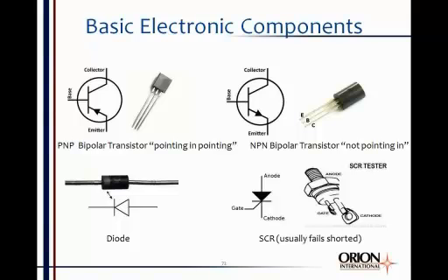We looked at diodes in circuits a little while ago. That's what a diode physically looks like, a little black round thing that looks like it's wrapped around the wire. You see the line? The line on the diode represents the schematic line, which determines the direction of current flow for that diode.